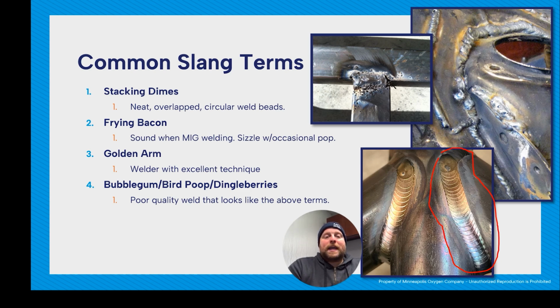Frying bacon, that's the sound when you MIG weld. It should be a sizzling sound when you're doing the short circuit transfer method with an occasional pop. That's telling you you're right where your settings want to be. There's a ton of listening and hearing that really can help out with welding once you start to key in on the different things.